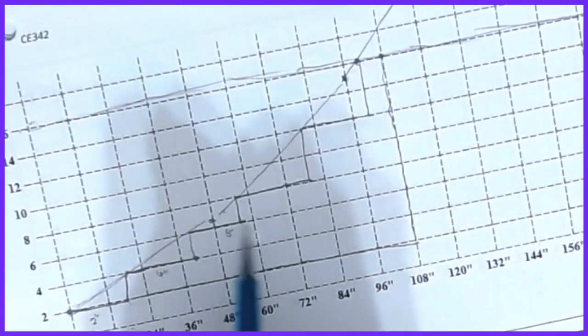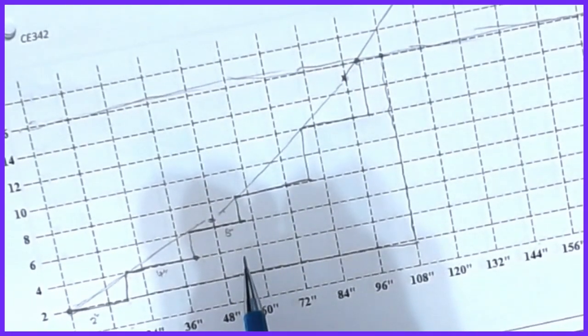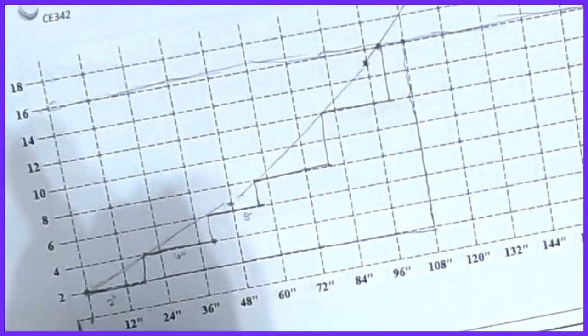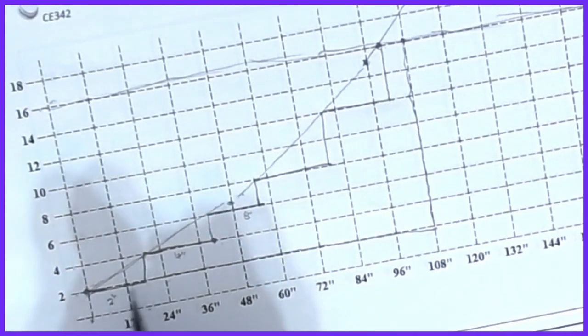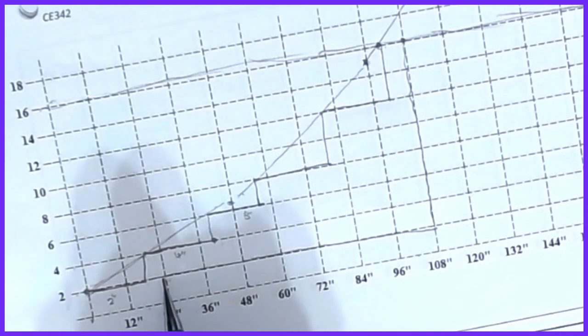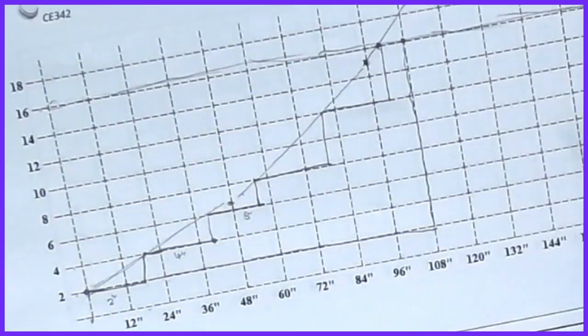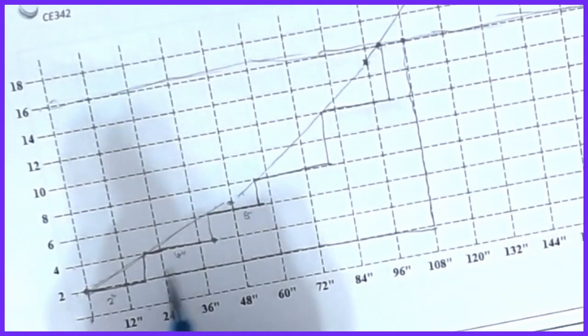And that's what I want you guys getting some practice doing. Now, there are an infinite number of possible answers that satisfy this. Again, try to think of that 24-inch rule, that you want these to be some factor of 24 inches, so that every time I end, I do things for 24 inches at a time. So 3 number 8s is 24 inches. I put 3 stirrups in, I'm 2 foot away, and then I can continue on. Okay, whereas with 2 inches, I would need 12 of them, and with 4 inches, I would need 6 of them.